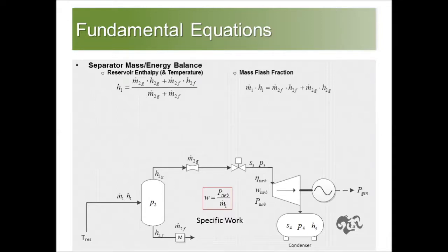Starting off with the same energy balance, you can solve for the mass flash fraction. Throwing in the mass balance gives this. Rearranging, substituting in for the enthalpy of vaporization, dividing through by the mass flow entering the separator, and solving for the ratio of the steam flow out of the separator versus the brine entering the separator gives this. On the San Jacinto project, we were getting a very respectable 31% or so mass flash fraction. Again, this may be a worthwhile parameter to have the DCS calculate and trend over the life of the plant.